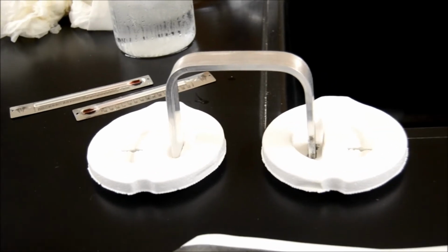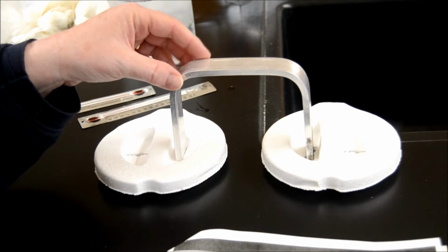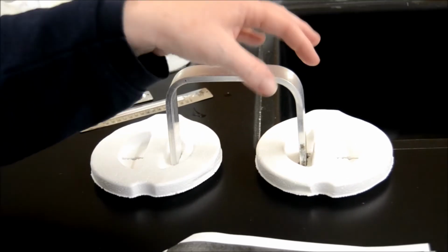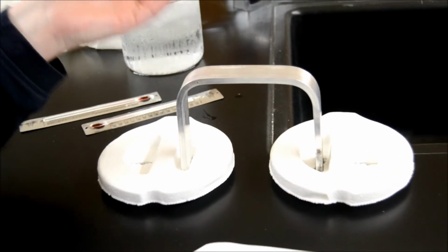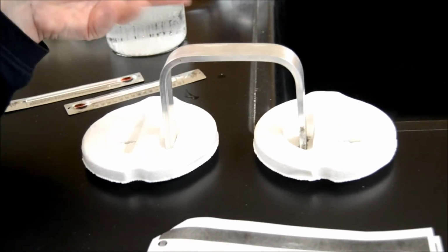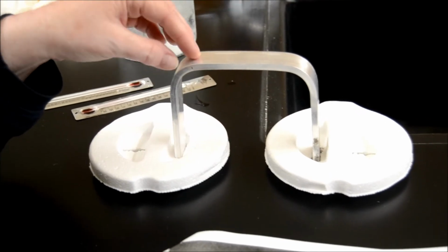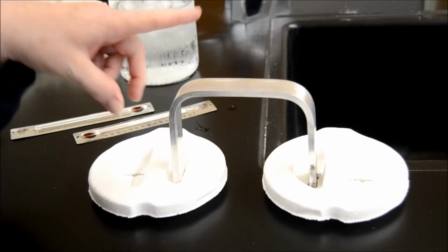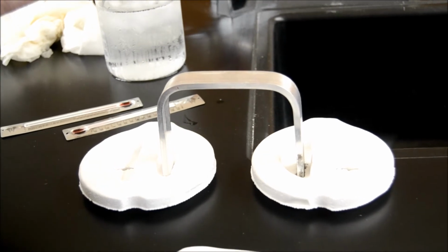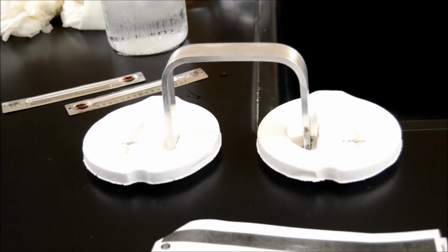And the whole idea is, since this is not insulated, that's why you're losing heat. But if you elongate it, it gives more surface area for you to lose heat to. So if I had elongated this aluminum bar, that means that your cold would have changed less, because more surface area is exposed to the atmosphere, and since it's not insulated, you would lose even more heat. All right, hopefully this helps.